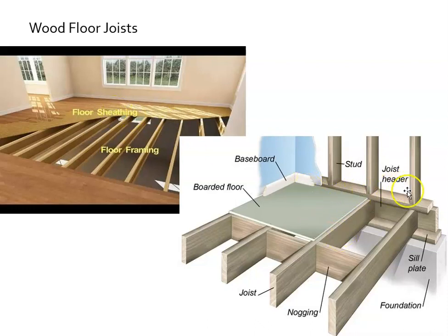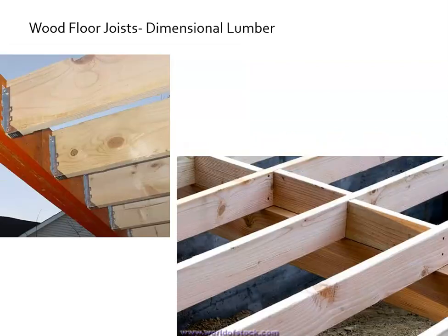And then this sill plate, this is the one thing I don't like about this detail. This subfloor would be underneath that sill plate. All right, so that's another red flag for this detail. And then we could see some joists happening there as well. So not too much to describe there.